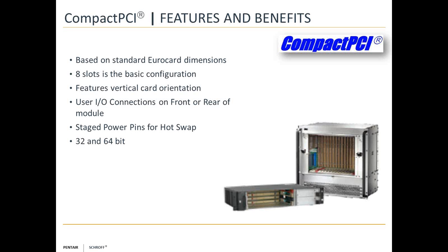Compact PCI features vertical card orientation for efficient cooling and positive card retention with front metal panels. It has user I/O connections on the front or rear of the module, and has staged power pins for hot swap, and it's available in either 32 or 64-bit versions.